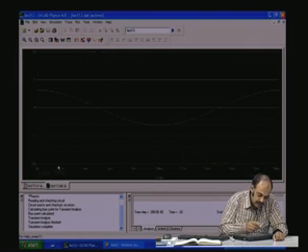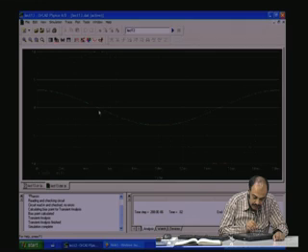The red one is the voltage that you are applying, you see that it is starting from 0, and the current through the capacitance is already at the positive peak, and then it goes down, cuts 0 at 90 degrees corresponding to the voltage, and then reaches the negative peak when the voltage is 0, and so on.